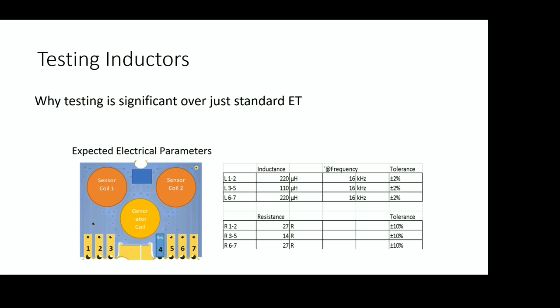Absolutely. I can't stress the same thing enough. Looking at your example here, where we're talking about inductance in the first example of L1 to L2, 220 microhenry, frequency at 16 kilohertz. Well, what happens, as I talked about at length there about coils and caps and reactance, if something happens in that resistive R1 to R2 resistance, you're going to change the inductance. And what's going to happen is at your 16 kilohertz, you're not going to be getting the response that you're looking for because you have changed the resistance.